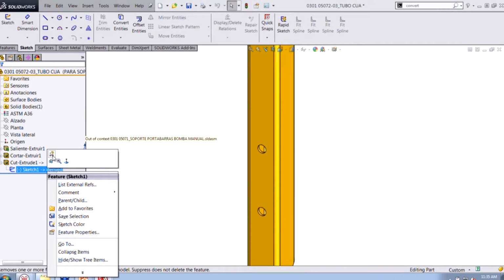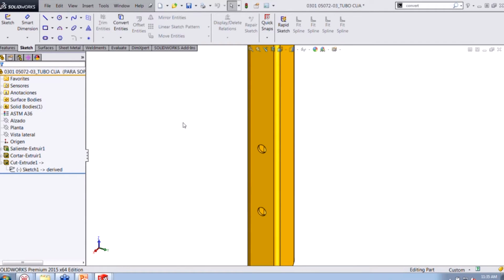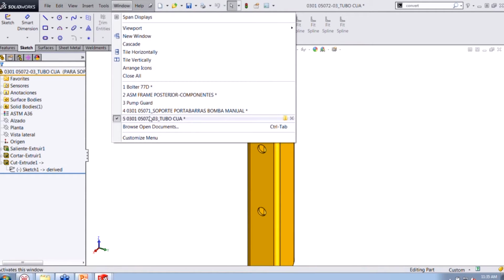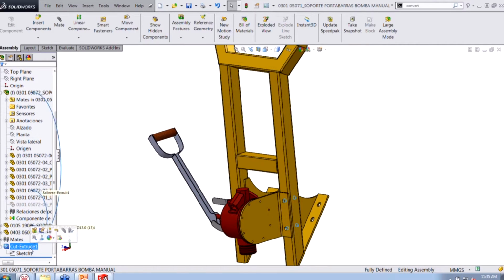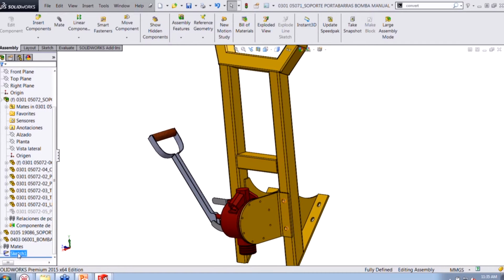it's at the assembly level as an assembly feature. So what happens if you run into a scenario where you want it both in the assembly as well as in the part, and you want to be able to modify it at the part level? Okay, that's where you're going to have to do it in context. So if I pop back over here, what I'm going to do is delete that assembly feature as well as that sketch.